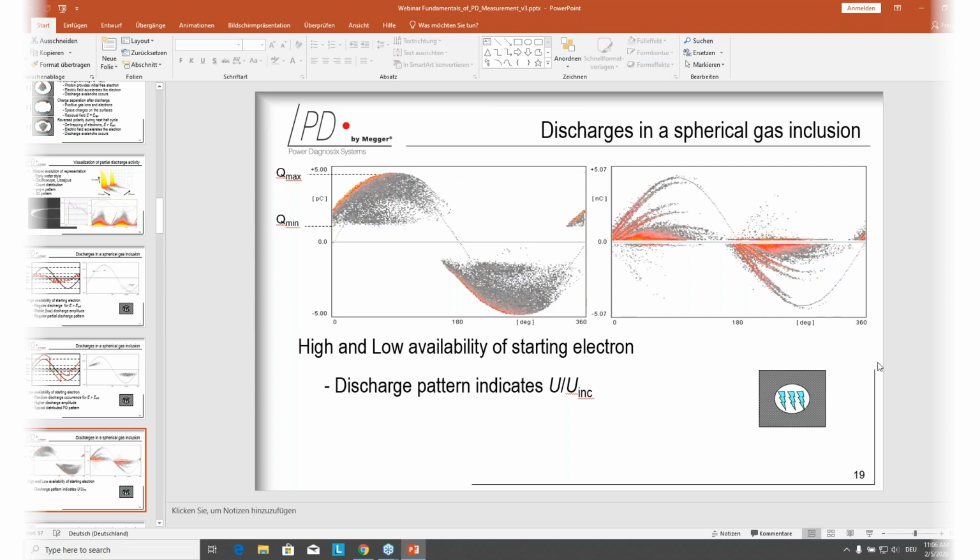The next is about whether IEEE standards exist for PD measurements. That means, are there available standards out for partial discharge measurements? Yeah, the answer is yes. There are multiple standards out from IEC and IEEE, including PD measurement methods and procedures for testing high voltage assets, mainly in the factory for quality acceptance tests.